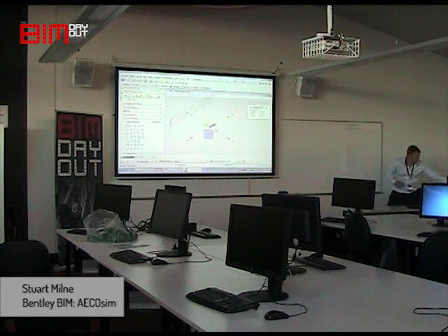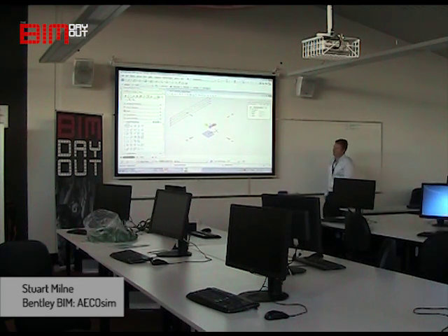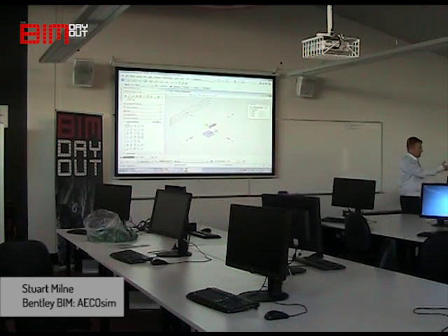Now, the first message it says in the lower left-hand corner is define the length. So what we need to do is rotate that compass around. And to rotate it so it's lying flat along the floor, you type in the letter T, just like that, and you'll see that that AccuDraw compass lies flat on the floor. And before you hit T, it's actually physically looking at you.